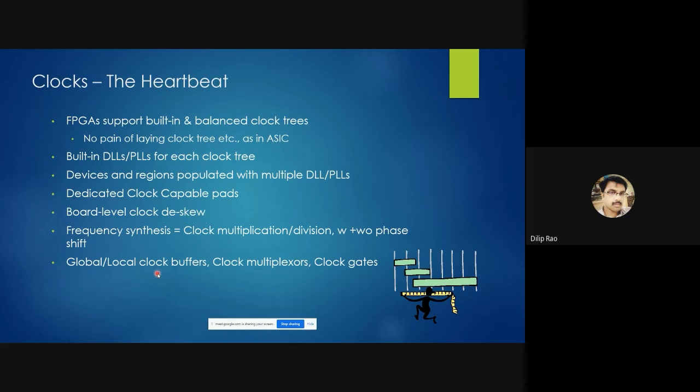For that, what the tool offers is a clock multiplexer in specific, meaning on the clock network itself there is combinational logic implemented that acts as a multiplexer. Instead of writing a logical multiplexer, you can choose to instantiate the clock network multiplexer to avoid inserting skew to the network.